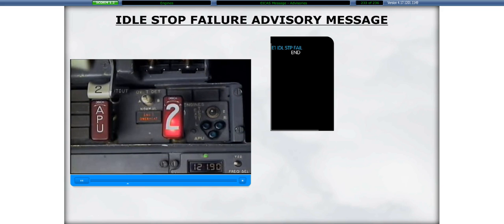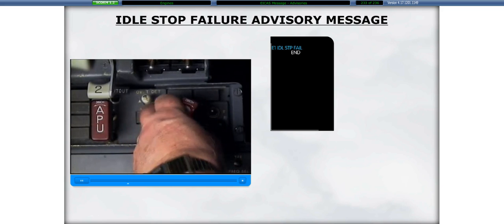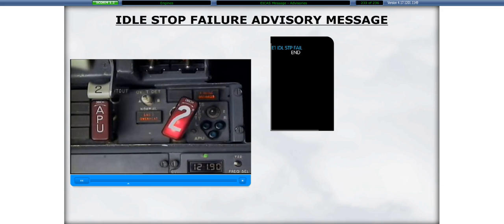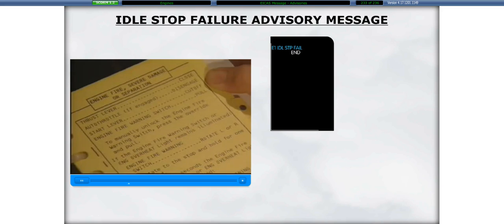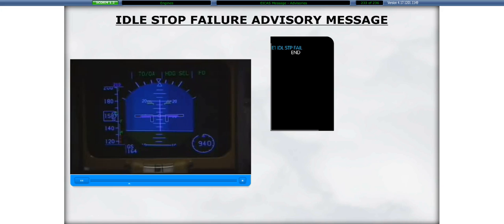Even if there is an actual fire, there is adequate isolation between the airplane structure and the nacelle to ensure sufficient time to establish and maintain airplane control to a safe altitude. Taking this time may cause further fire damage within the nacelle, but accident reports consistently show that flight path control must be focused on first, and it must remain a high priority until landing.